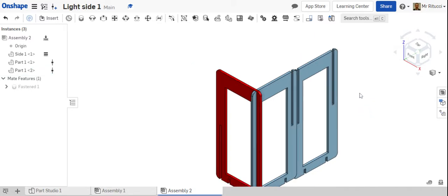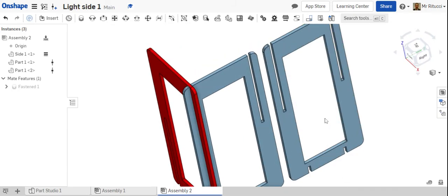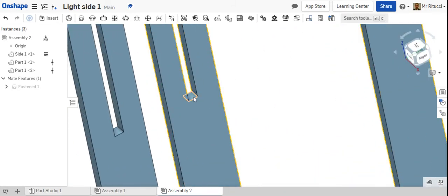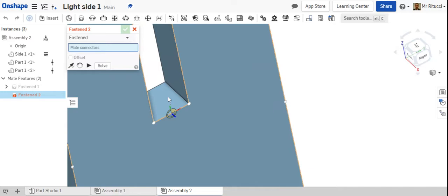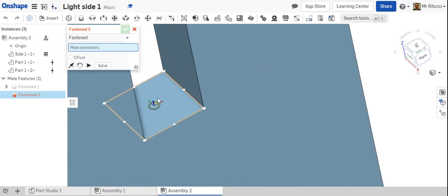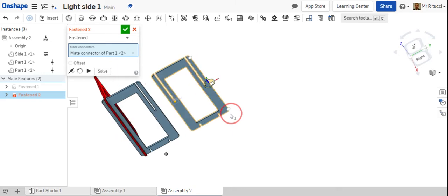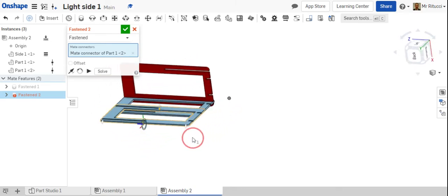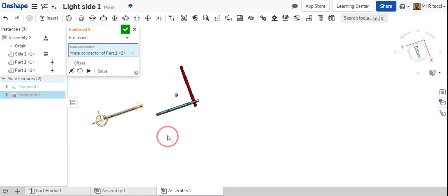So again, we're thinking, right, this time I need to zoom into this one. I want to get that face and attach it to the other place. So again, it's a bit of a repeat process. Click that one, fasten mate. You're going to select it there. So the blue line's pointing up, and that face is selected. So that one's ready, that's active. Then I'm going to spin round, right click on the mouse, orbiting round, and I'm going to aim for this little area here.